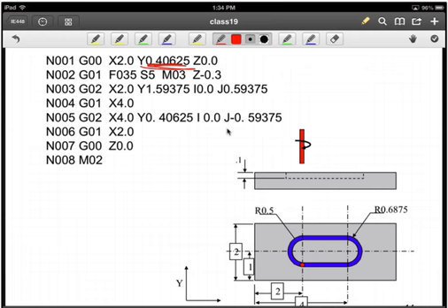The other thing we should note here is we're going to have a problem because we can only have 4 digits after the decimal point. And so this will be flagged as an error, this last 5, which means we're going to have to round up or down, and the question is, which direction should we go? We also see that with the other corrections that we'll have to make, the exact value cannot be represented in the G-code, and therefore there's going to be some round-off error, which will affect, obviously, our final result.